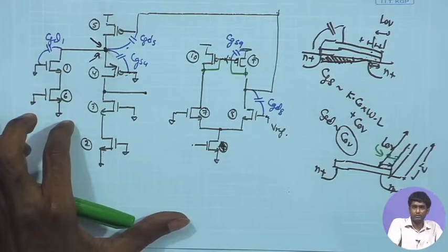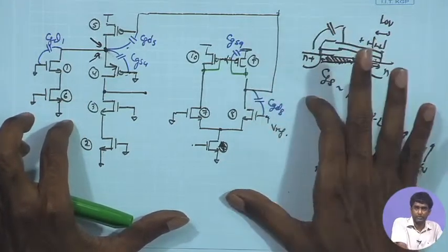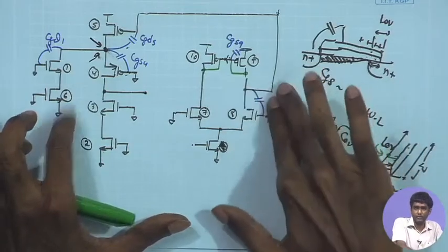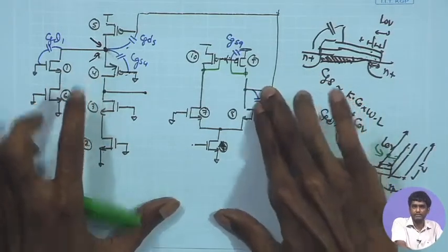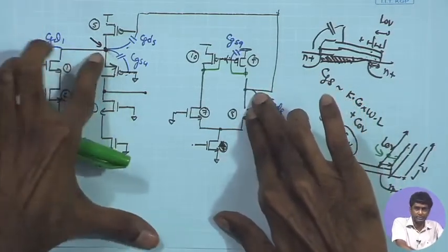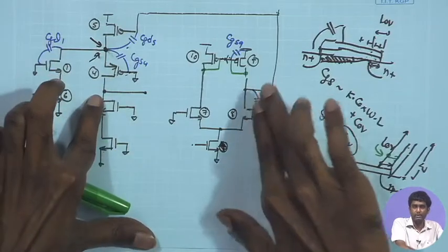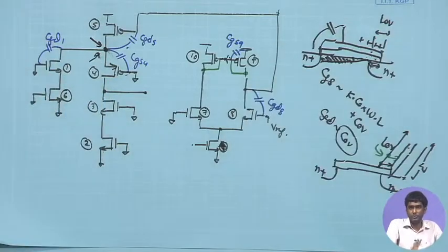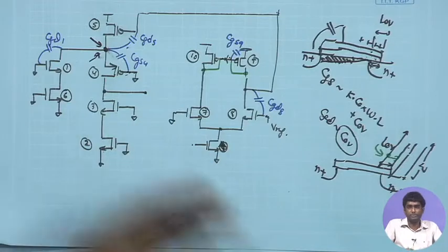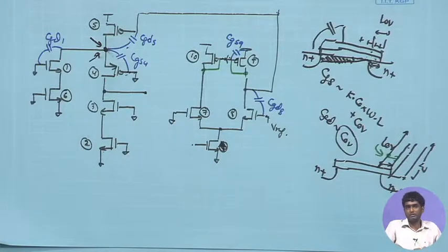So, that will mandate that, okay, then you add another capacitance over here, and then try to compensate this one as well as this one, so that this does not become the non-dominant pole, this stays the non-dominant pole, this stays the dominant pole, and this is significantly lower. So, all those constraints we can definitely look at in simulations and observe the phase margin coming up.